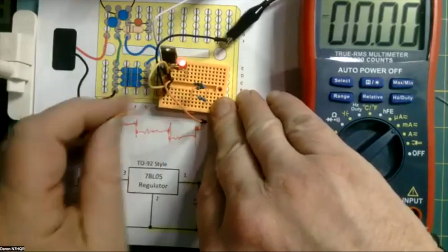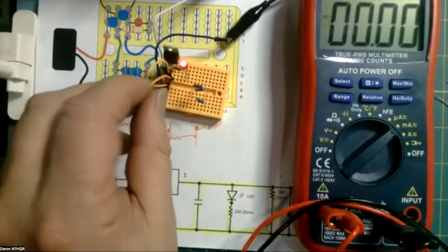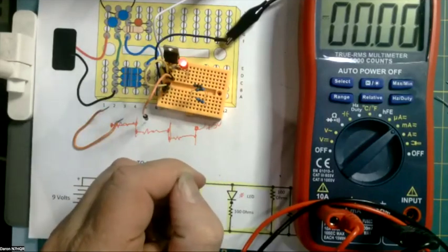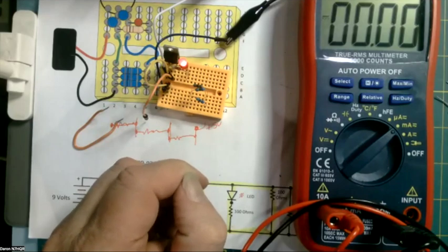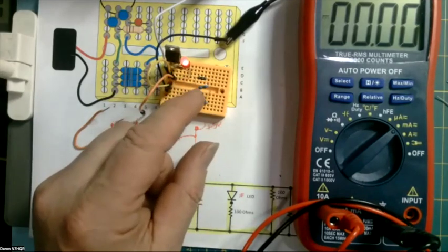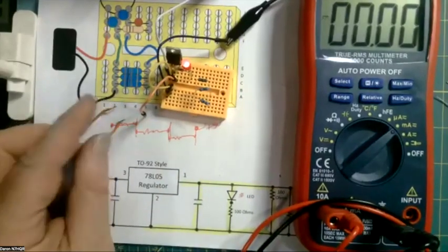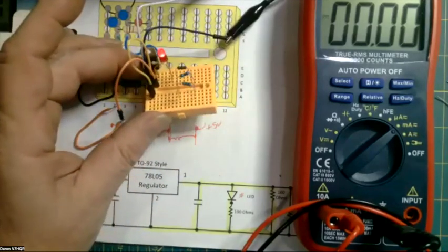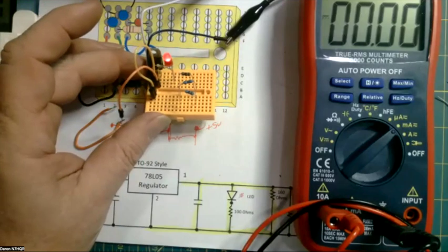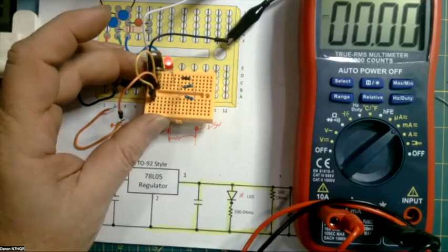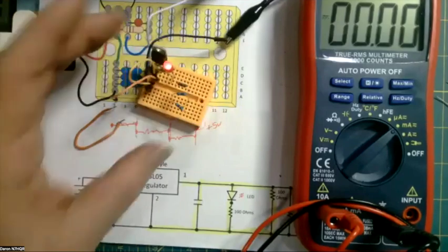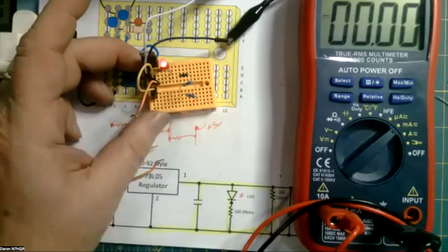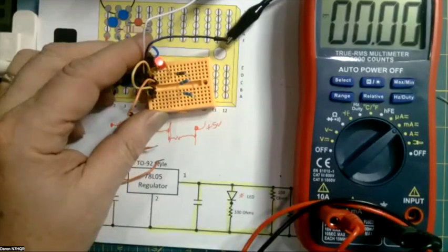Now, does everybody understand why I talk about watts and the power of a resistor? I mean, we took a quarter watt resistor, put it across 5 volts with 10 ohms, and that's a half an amp. So a half an amp times 5 volts is 2.5 watts in a quarter watt resistor. That's why it smoked. Yeah, that one got a little dark there. Not gonna be good. Well, you smoked that one a lot quicker than the other one the other day. Yeah, that one went pretty fast.